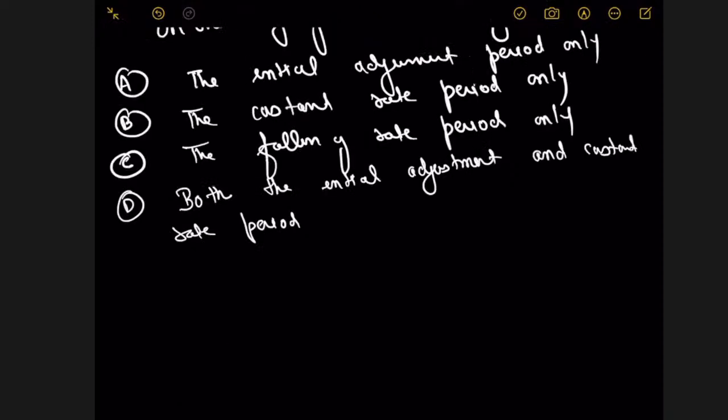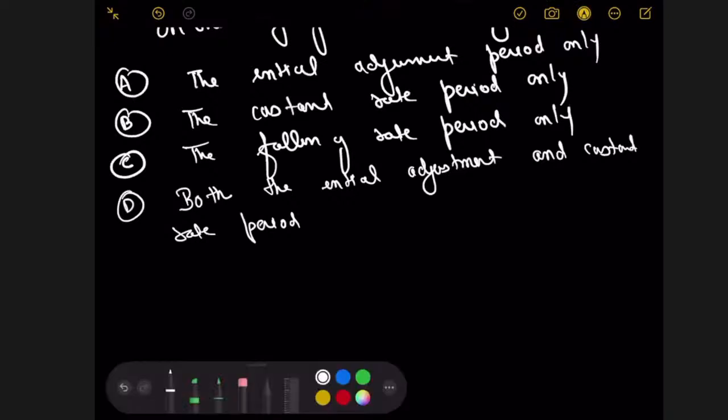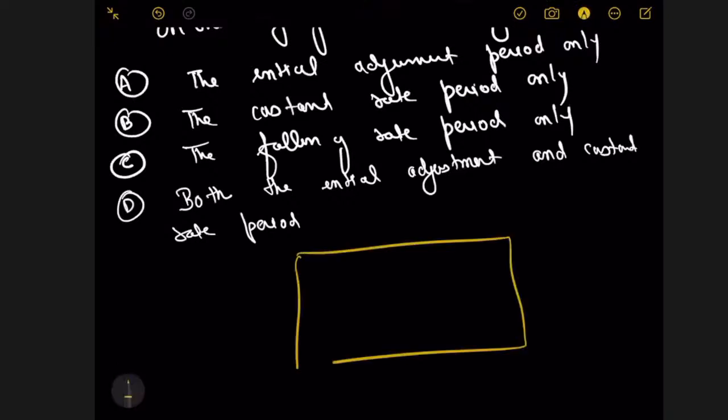So there is an interesting graph from the drying section. You should remember this actually. This is the unbound part, and this is the constant rate period. Then there is the falling rate period. Then this is X star critical. This is known as unbound and this is bound. Here it is free moisture content. So this is the thing.